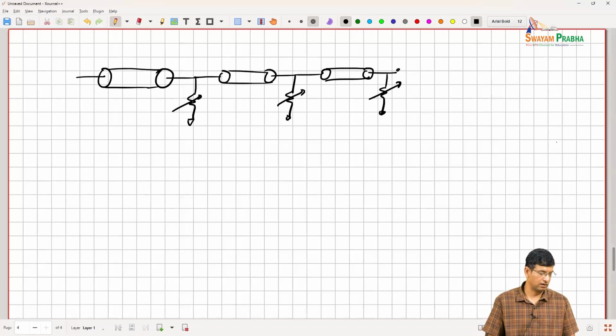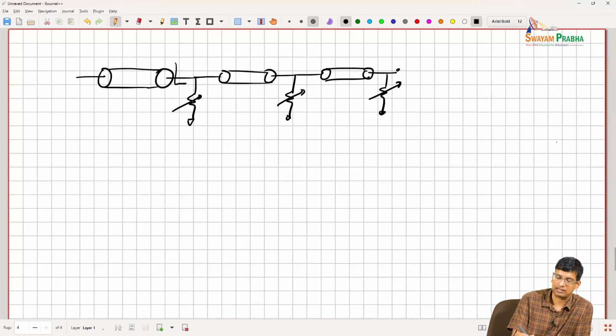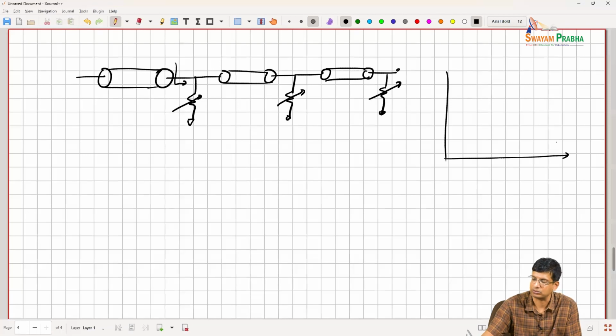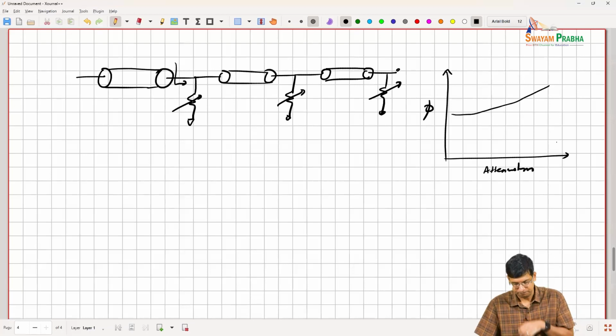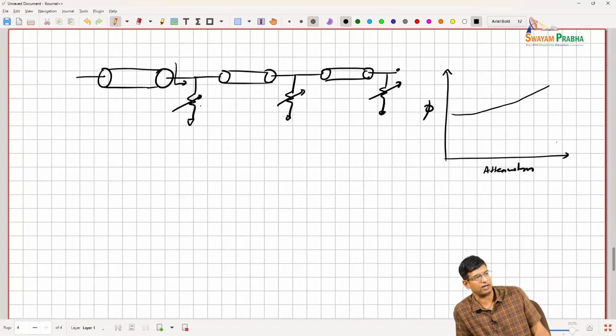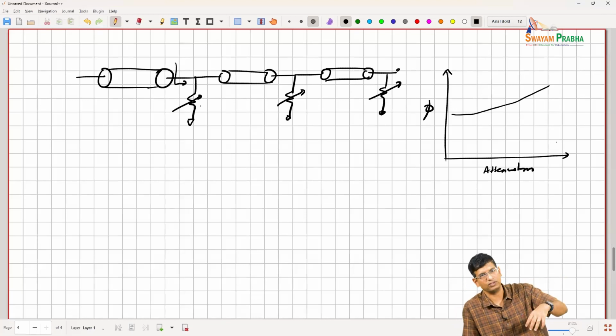The challenge here is, of course, that this is effectively changing the impedance of the line looking here, right? So you're going to see the same situation where if I look at attenuation and I look at phase, I'm going to start seeing a non-uniform phase again instead of a constant phase, particularly if I try to make this R very small to get a lot of loss from just one shunt resistor.